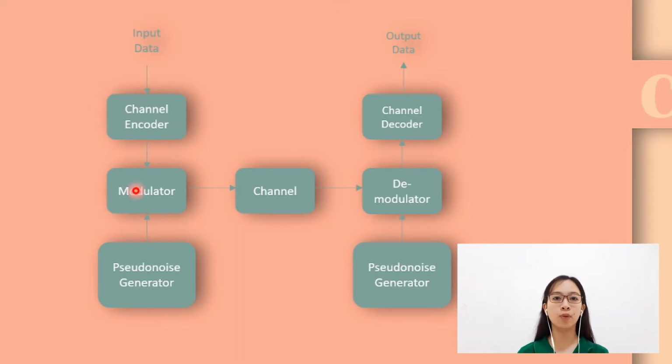Then, the signal would be modulated further in the modulator or spreader using a coded sequence of ones and zeros with certain autocorrelation properties, called a pseudo-noise coding sequence, that is generated by a pseudo-noise generator or deterministic algorithm. This noise is a maximum length sequence, which is a type of cyclic code, and only the receiver can decode the signal since it is required to know the algorithm and seed to predict the sequence.